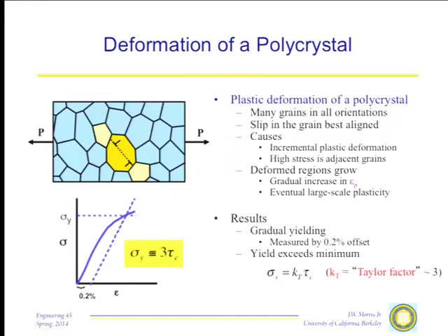If we turn to a polycrystal, as we discussed last time, the yield strength of the polycrystal is going to correspond to the following. Imagine it's completely relaxed, these grains are under no stress at all, which, as I said last time, is an unusual situation. Usually, if you make a polycrystalline material, just because of the way you made it, there are residual stresses in the material. Some of those stresses will act to favor plastic deformation and lower the yield strength. Some will oppose plastic deformation and raise the yield strength.